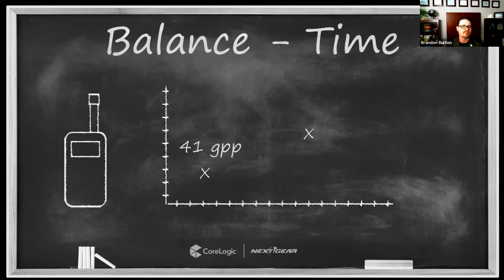Let's not worry about that for a moment. And let's say that that second reading, after a period of time has transpired, now indicates a higher grains per pound, right? So this should bring out some really obvious red flags, all right? Hopefully it does, that I've taken a reading and then a certain amount of time transpires and humidity is now increasing over time, right? The amount of moisture in the air is now greater. This is problematic. Unless it's intentional, it's problematic because this indicates that there is not an appropriate balance in my drying environment, at least not over time. There's not an appropriate balance.